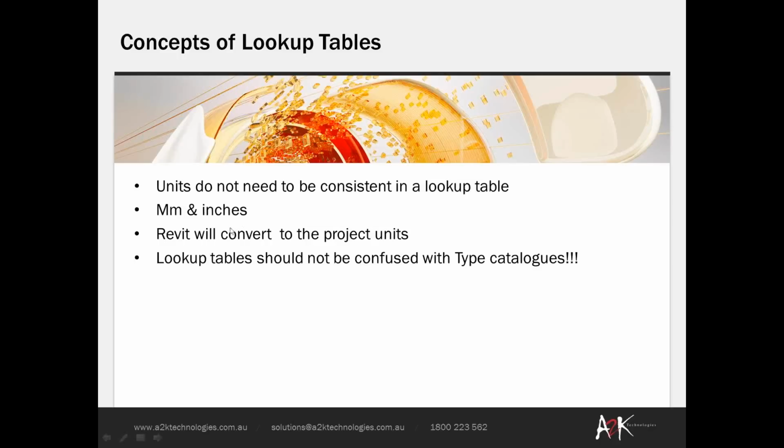What will happen is that when Revit uses this lookup table in a family, it will convert any of the units to the actual project units that are being used within that project at that time. Okay, so just keep that in mind.